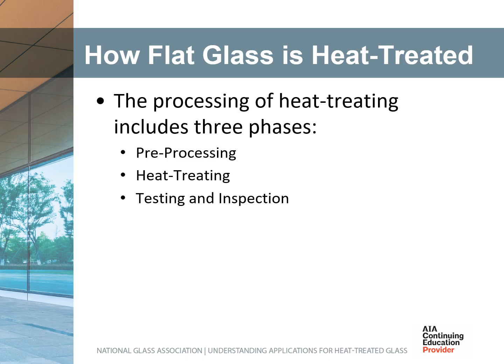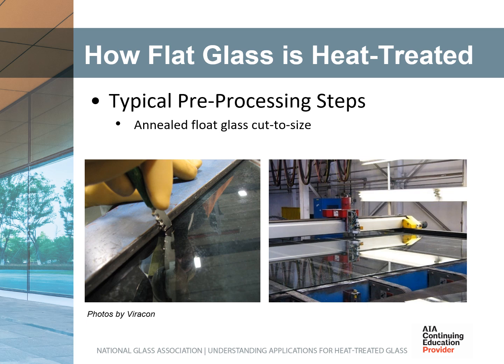Testing and inspection include specific visual inspection criteria as outlined in ASTM C1036, and for fully tempered glass, completing the safety glazing testing criteria outlined in ANSI Z97.1. Before the heat treating process can begin, annealed glass must be cut to the finished size or a processing size for further fabrication, such as polished edges.